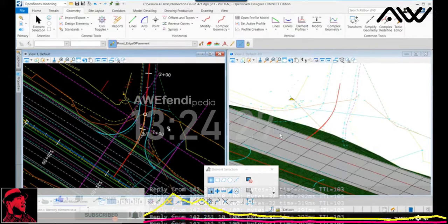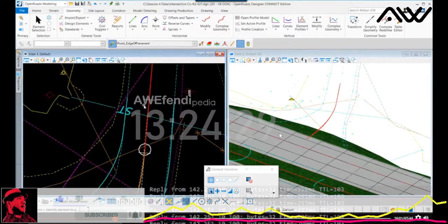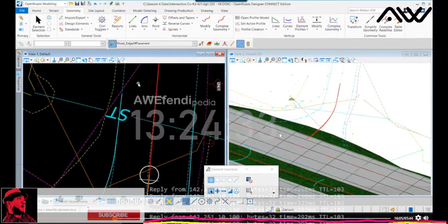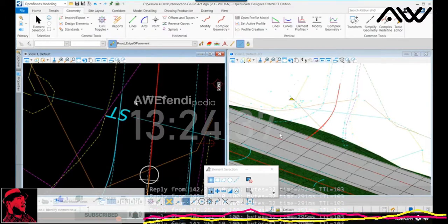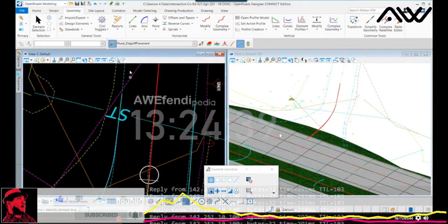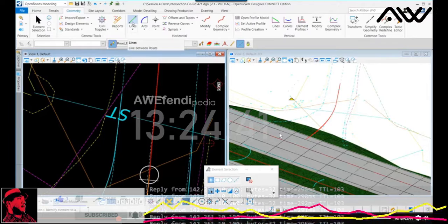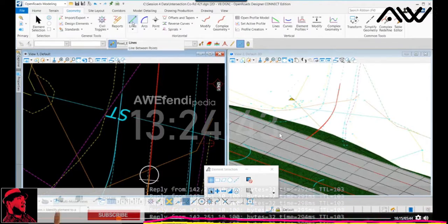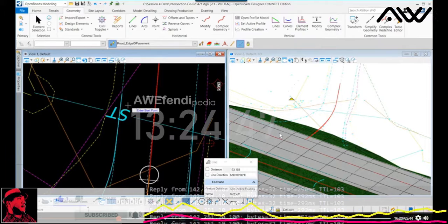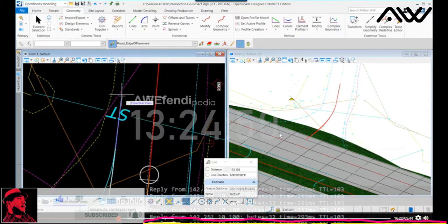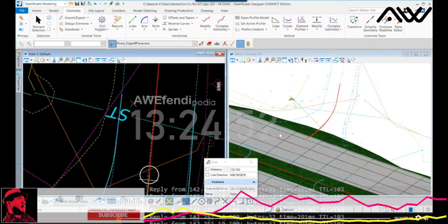Now we're going to continue working here, recognizing that ultimately I am building the boundary elements. Those edge of pavement features will also be used as boundary elements for a pavement terrain. So in recognizing that, I'm going to again use the geometry tools. I'm going to place just a straight geometric line, and I'm going to snap that from the edge of pavement.